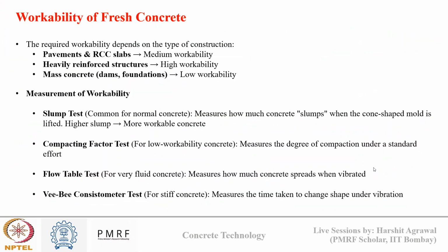Now, for different types of construction work, my workability requirement can change. Like for pavements and RC slab, it is not RCC, we generally say RC slab, we require a medium workability. For heavily reinforced structure, I require a high workability. And for mass concreting, like for dams and foundation, I generally require a low workability.